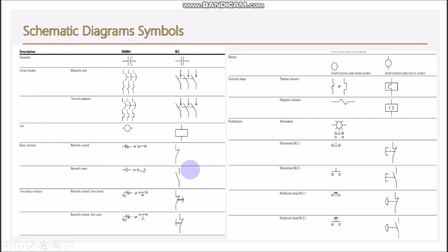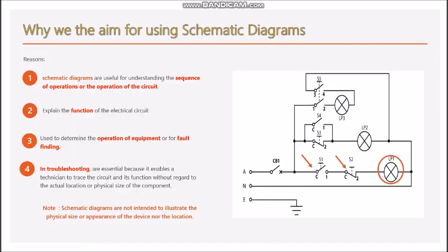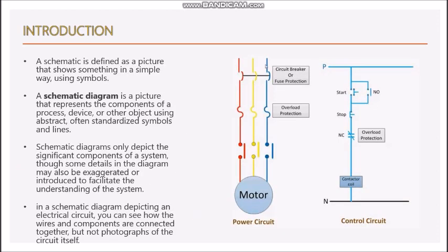We need to talk about this first. We must understand that in schematic diagrams, all the circuit here must be drawn non-energized. So the switch during normal operation, non-energized, without any push button pressed, is already normally open. This contact is normally open, and this switch is stop, so it is already normally closed. We draw all our symbols in the non-energized situation.